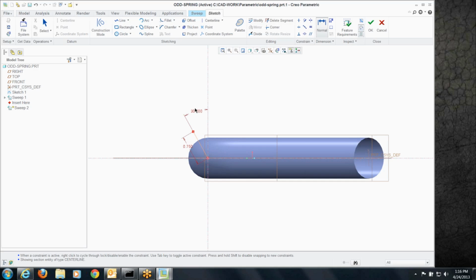Well, what we can do is we can choose how we want the angle to change as it goes along that curve. Anytime you do a sweep, you've got a little parameter called the trajectory parameter, or trajpar for short. That trajectory parameter along the sweep from where you start to where you finish goes from a value of 0 to 1, no matter how long that sweep becomes. It's normalized. So we can use that in relationships. So if I want this line to pivot around its pivot point multiple times as we go along that trajectory, I can do that with a Sketcher relation.